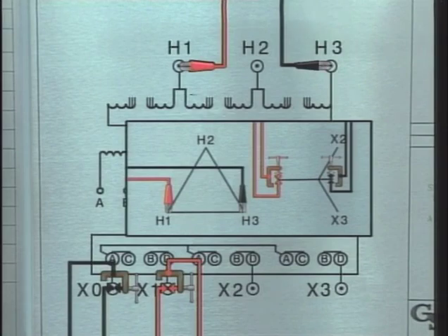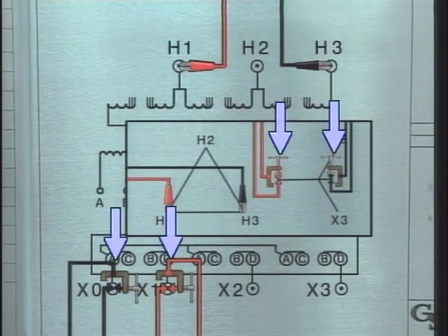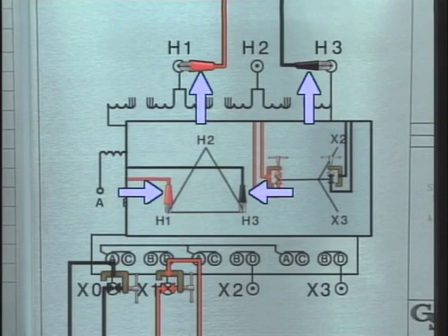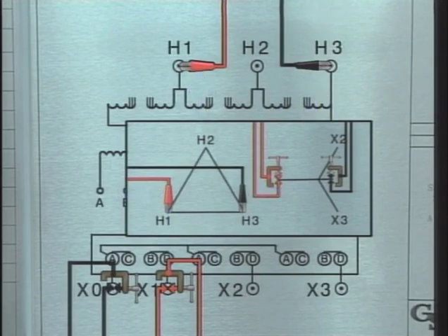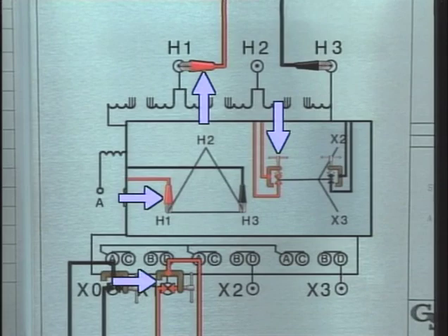The principles that we looked at for making test connections for a turns ratio test apply to most substation transformers. These principles included connecting the exciting test leads to the terminals of one winding of the lower voltage transformer windings, connecting the high voltage leads to the same phase winding terminals of the higher voltage windings, and making sure that the red test leads are connected to corresponding low and high voltage terminals. We also saw that the connection and bushing layout diagrams on a transformer's nameplate are very helpful in determining precisely where to make the connections for a turns ratio test.